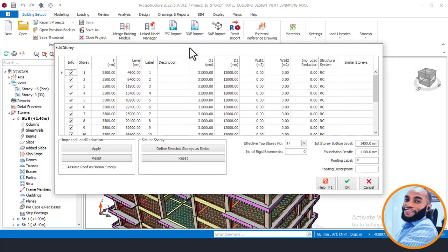But even if all the rooms in this 16-story building are occupied, there will be a time when all the lobbies and restrooms are free from human activities, because they are all in the rooms resting. So in this kind of place, the live load around the lobbies and most areas where human activities are not operating at that particular time is less.